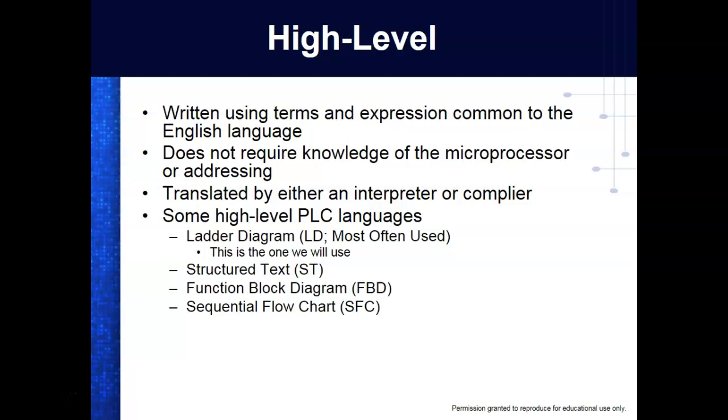We're going to pull instructions down from boxes. We've got a palette up there. If we want to put a normally open contact, we pull down a normally open contact picture. This is the predominant language. Probably over 95% of programs for PLCs are written in this language right here.